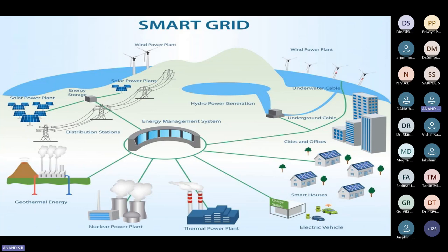And there also, the latest order came in Germany: whoever has rooftop solar needs to change the solar inverter, so that it can control the generation and control the injection to the grid, whenever the grid requirement is there, based on the signal received from the SCADA center. And whichever inverter is not complying after a particular date, I think it's about 2 years old now.